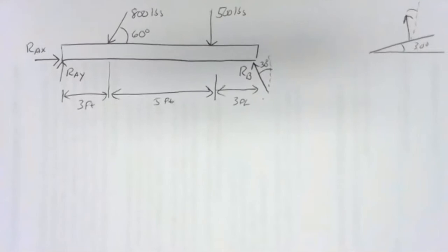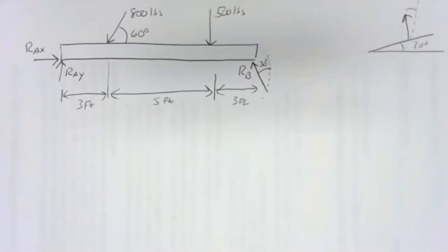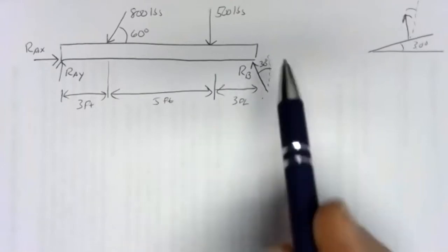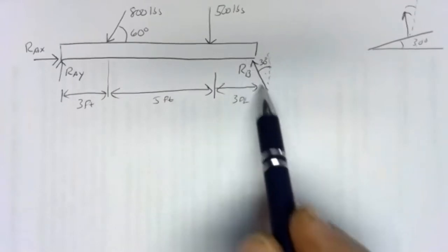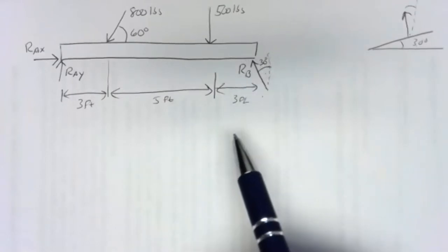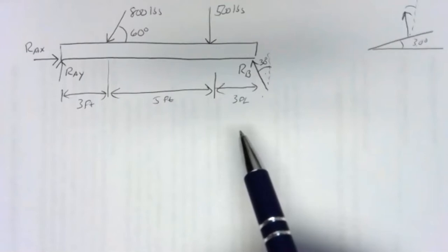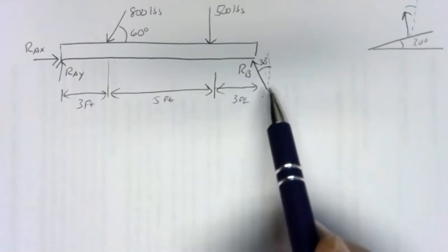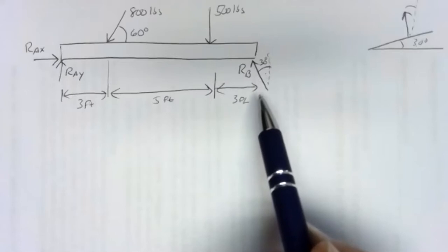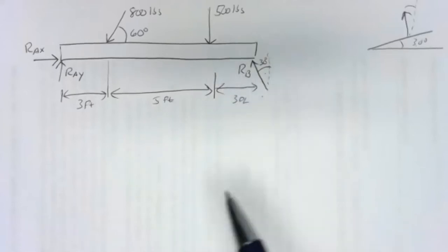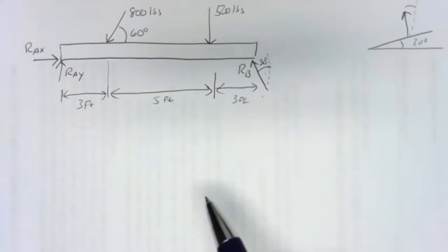So there's our free body diagram, and we'll see how we can work that out in a moment. Does the free body diagram make sense so far? The sticking point's usually how to represent this reaction force, but once you lock into that key fact that the roller applies a force perpendicular to the surface that it sits on, that usually is enough to resolve the issue.